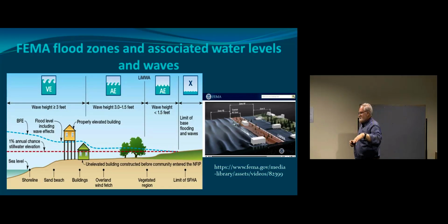And eventually, at the very back where the 100-year flood intersects with topography, the flood wave amplitude goes to 0. So the examples here show two houses, right? Two structures. This structure is really impacted. No matter how you do it, that's gone, right? His neighbor, although he's a little crazy, has his house a tad bit high, spoiled the view of the people that are further up. What happened is that house has been elevated to avoid that risk. And that's one of the solutions that's used, particularly for residences. The picture on the right shows that in more graphic form.